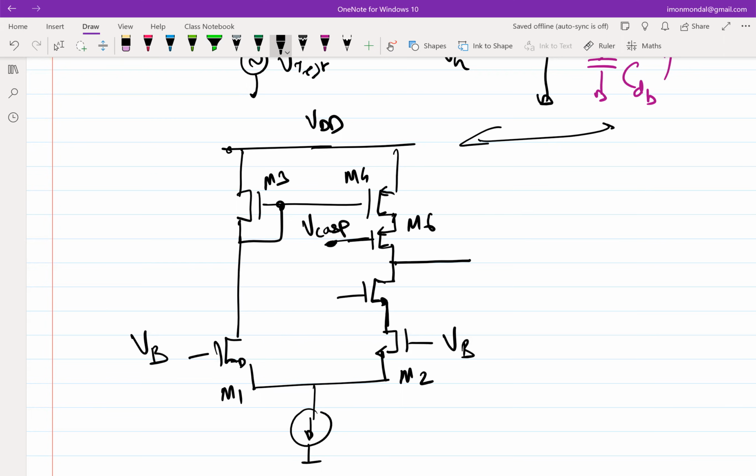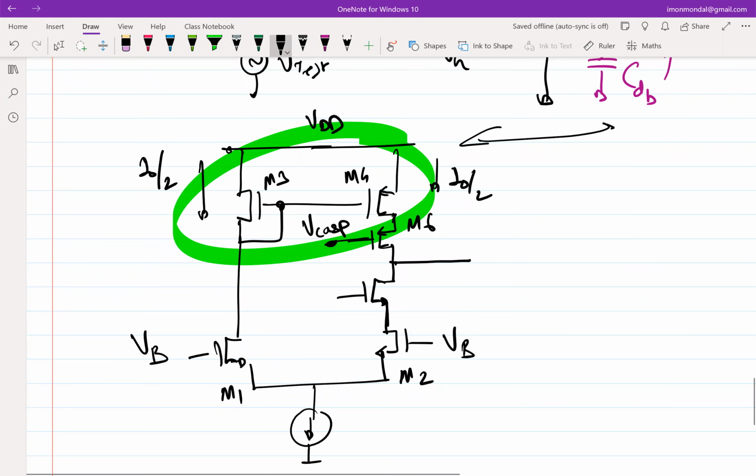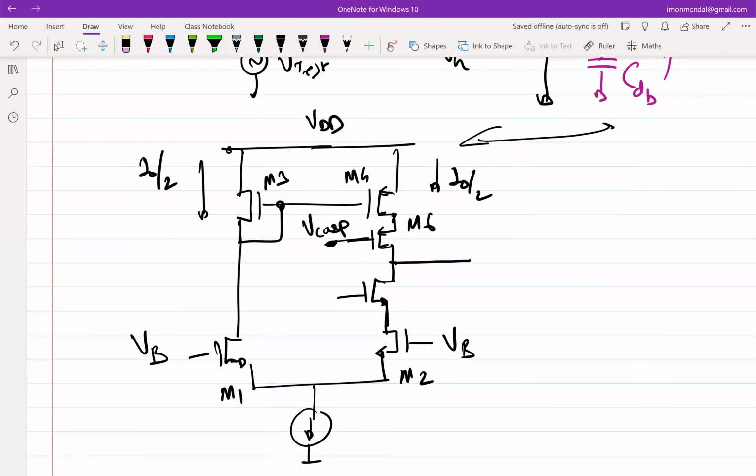I can do another direct connected MOSFET because I know I have current of I0/2 flowing. So this essentially is a mirror. This is a current mirror, right? And we have spent 1 or 2 classes on designing current mirrors. So you can take your pick, whatever you want. The one that we did in the quiz, the wide swing current mirror, might be a better thing to do because you don't compromise on swing. So how do I put this wide swing current mirror?